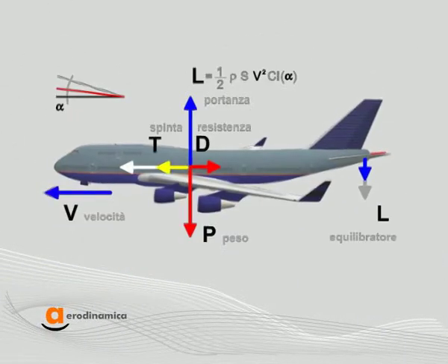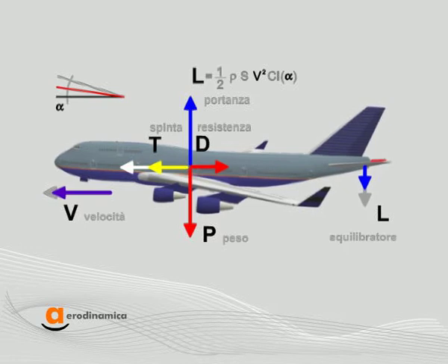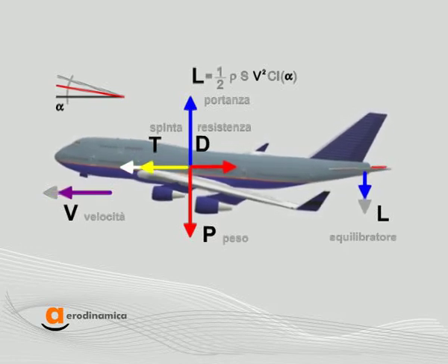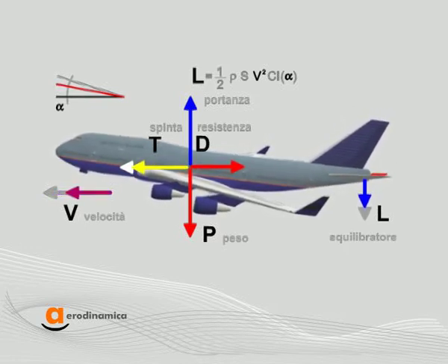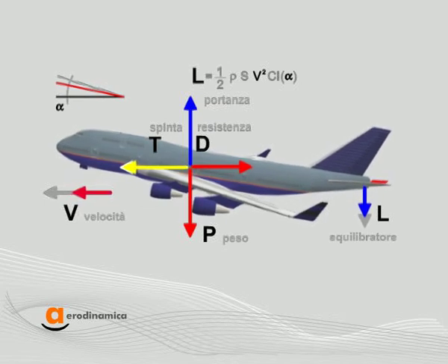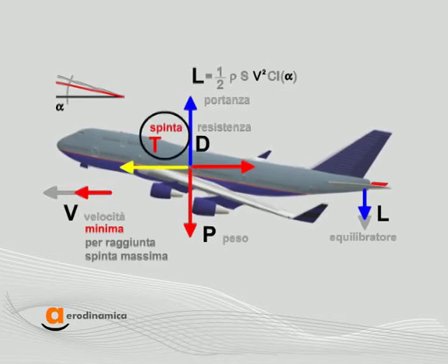It may also happen that by increasing the angle of attack, the aerodynamic drag increases and a higher thrust is needed. The thrust can be supplied up to a maximum after which drag cannot be overcome. In this case, the minimum speed is due to the max thrust. The minimum speed is due to the fact that the engine has reached its maximum thrust.